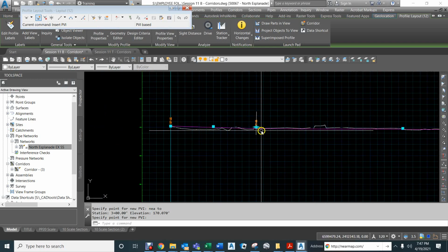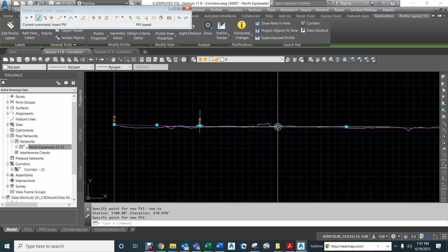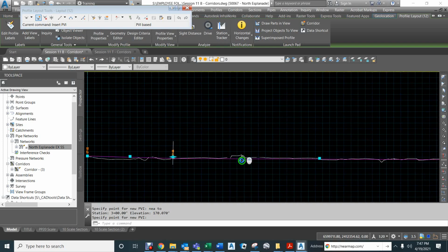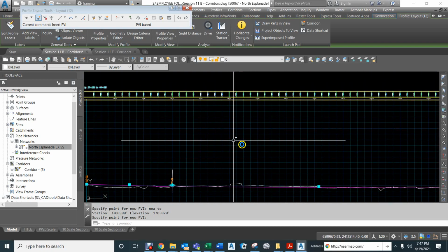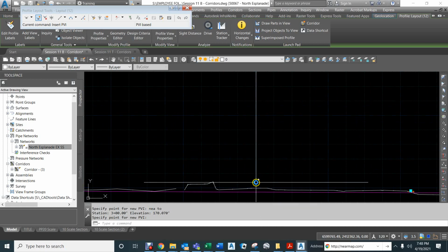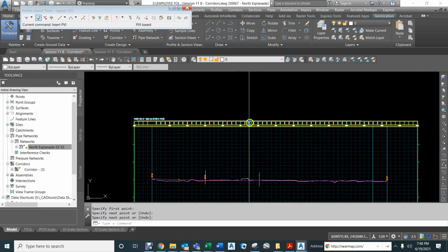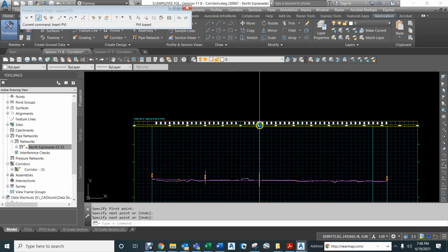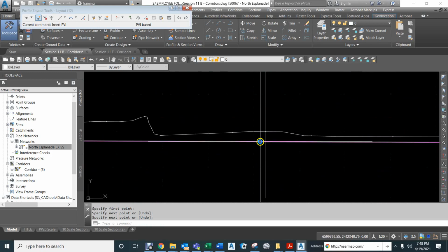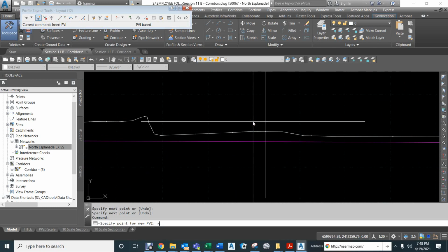So we have a negative 0.3 here, but then we're going to come up just a little bit, probably in 200-300 feet. Let's use this line right here, basically this area, and I'm just trying to mark it so I can put it on an even station, because I like my stuff on even stations. Then I'll add another vertex, and it'll be up here somewhere.